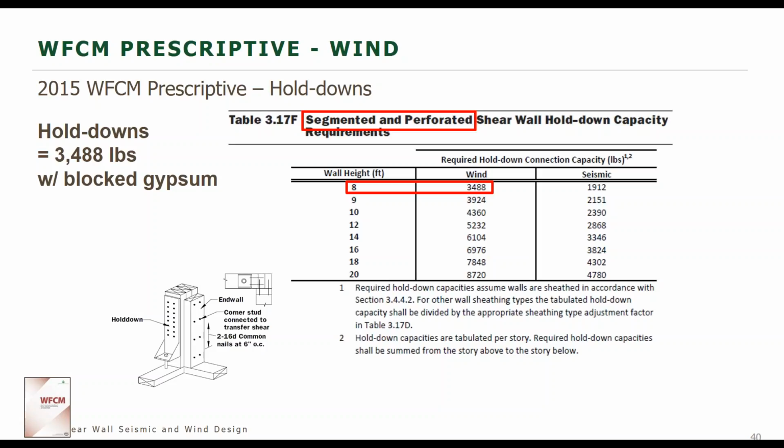For SDPWS, you can get some capacities for these screws, and if you look at them and see that they're comparable or above the capacities that we assume in the Wood Frame Construction Manual, then you could potentially use those values per the Wood Frame Construction Manual as well.